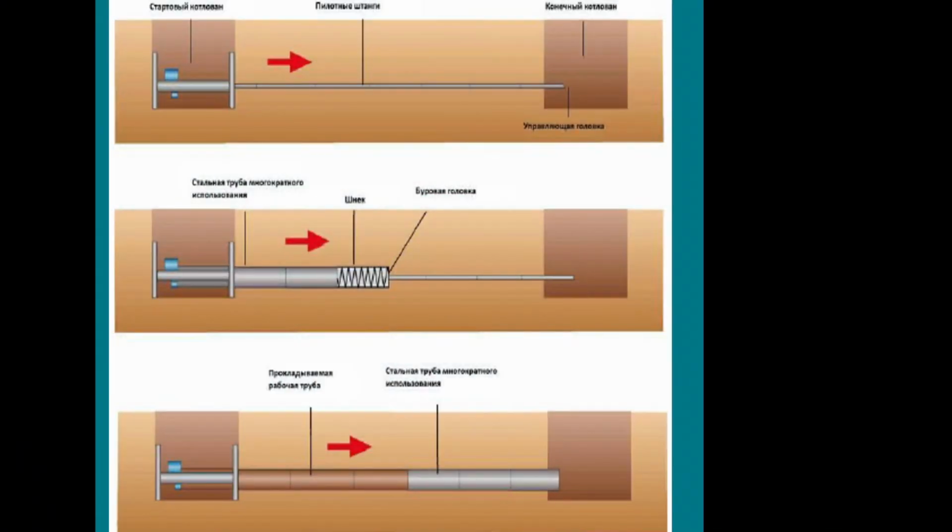Refer to the figure. With the auger boring rig, it is possible to implement pipe laying of steel cases, concrete or polyethylene pipe with diameter from 100 to 1720 mm on distances up to 100 meters, depending on the soil type. It is necessary to have two ditches, as also required in the process we discussed before, starting and adaptive, with the depth lower than the pipe laying depth by 0.5 to 1 meter in order to release laying communications.